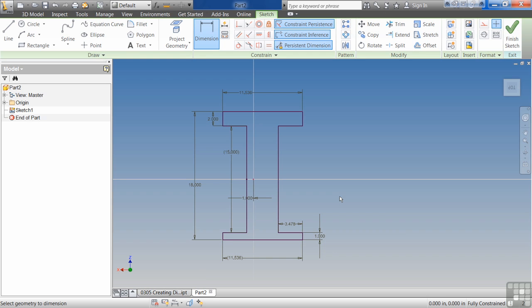You always think, oh, I'll never come back to this sketch. Once I create it, I'll be done. But there'll always be something you'll need to come back and do. So try to make sure that you limit the amount of dimensions and constraints and do it in as few steps as possible. One of the things I always tell my students is whenever you dimension something out in a sketch now, go back and look at it a year from now, and you'll laugh at how much you've come in a year's time, because you'll use so many fewer just from experience. It's one of those things you need to play with and get good at. And that's pretty much it for the basic guidelines.